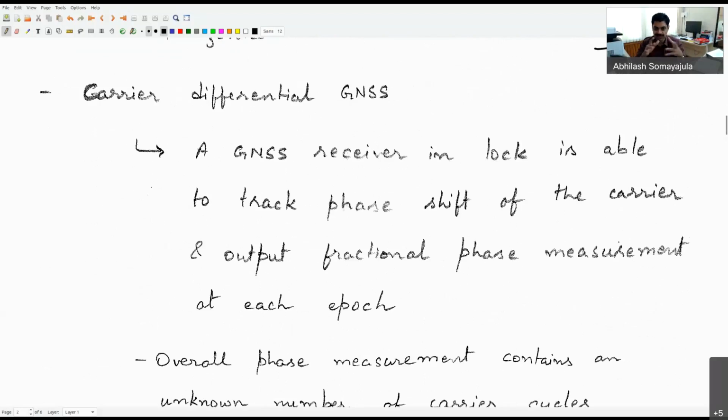If my observer was stationary, I should see that the phase continues to be the same no matter what. Once there is a phase which I have identified, let's say the carrier signal behaves as A sine omega t. Then that omega is fixed and my phase difference is 0, and it should remain the same for all future times. Phase is not something which will change with time.